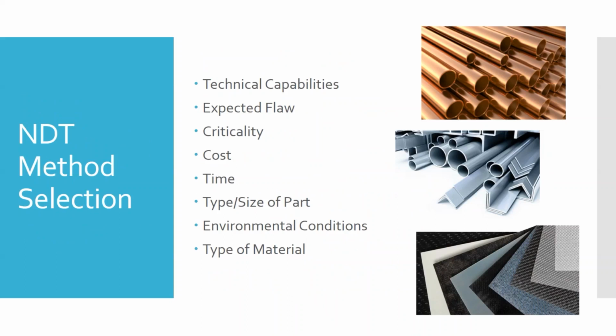So, technical capabilities. What do you have the equipment for? What kind of expected flaws? Are you looking for cracks, corrosion, delamination, disbonds? Is it a surface flaw? Is it a subsurface flaw? Different methods and techniques will work for different things. Criticality: how critical is it that you find it?